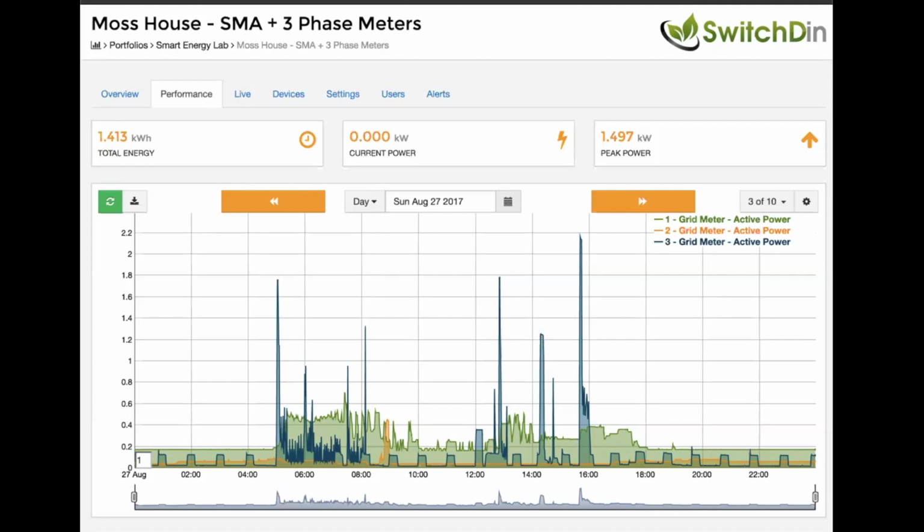Okay, so this will be specific to the installation you do. Like I said, as a designer, you can identify the coincidental loads, but of course they should be realistic. For instance, I've got a dishwasher and I've got a pressure pump. The chances are they'll both be on at the same time, because the dishwasher is going to draw water and the pressure pump will come on. So they're going to be coincidental demands. But I may put in my design that you can't use the arc welder at the same time as you're washing the dishes, and that's part of my design recommendation.